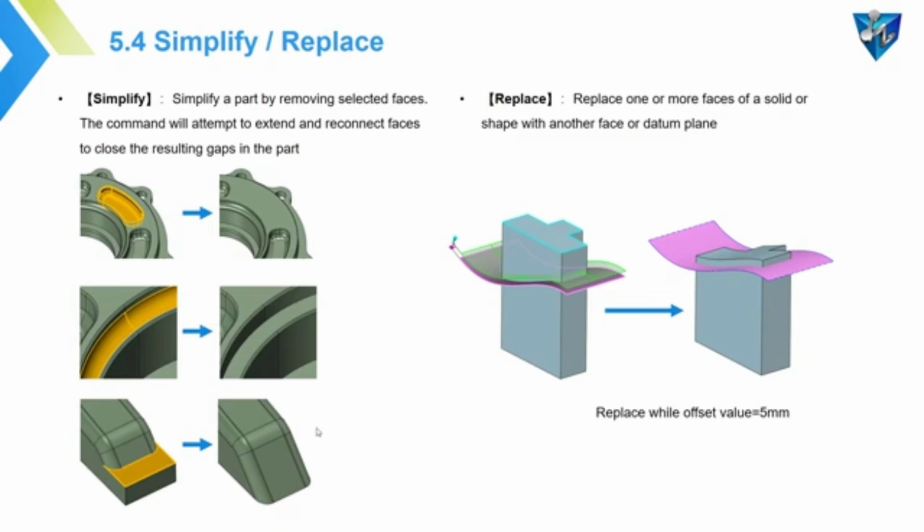used to delete some existing faces and reconnect faces to close it. You can use it to delete slots, fillets, holes, etc. For replace, we can use it to replace one or more faces of a solid or shape with another face or datum plane. This command is very convenient when you need to move a face to match a reference face.